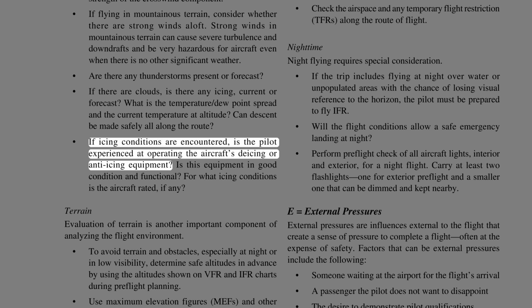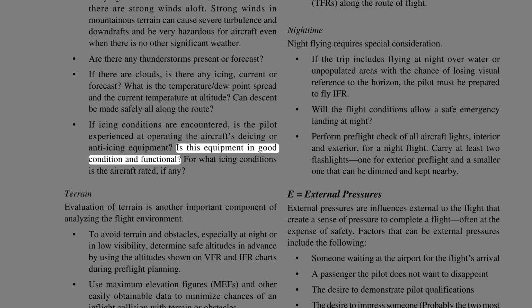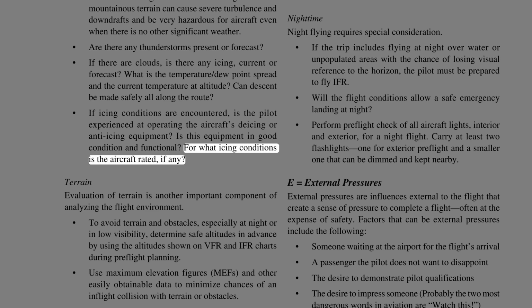If icing conditions are encountered, is the pilot experienced at operating the aircraft's de-icing or anti-icing equipment? Is this equipment in good condition and functional? For what icing conditions is the aircraft rated, if any?